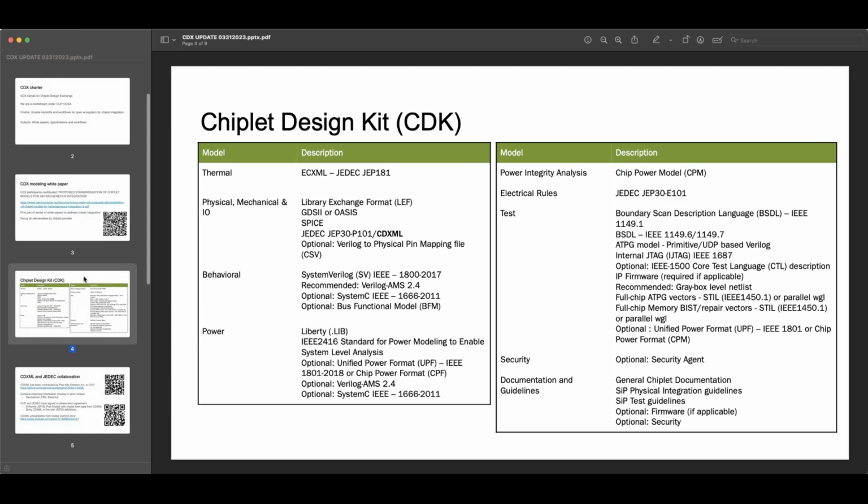They'll all be describing different aspects of the chip. For example, LEF will have all the bump locations, but the LEF will come from the die level, so you can look at the pin map and see where all the pins are.